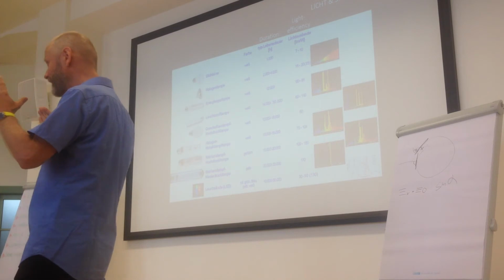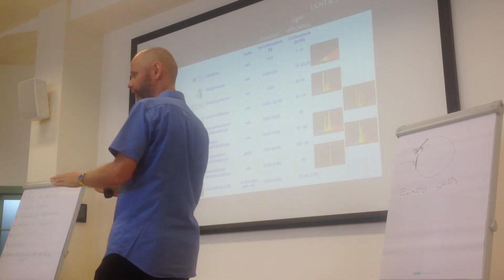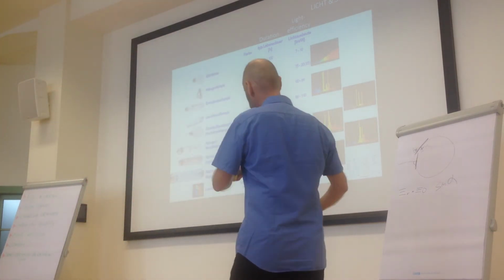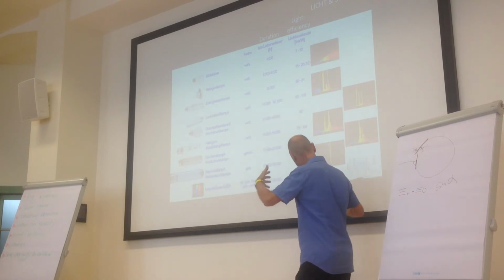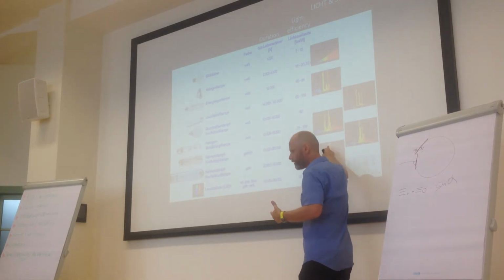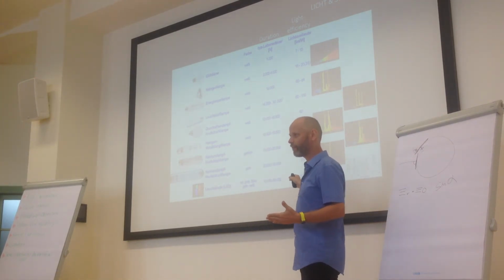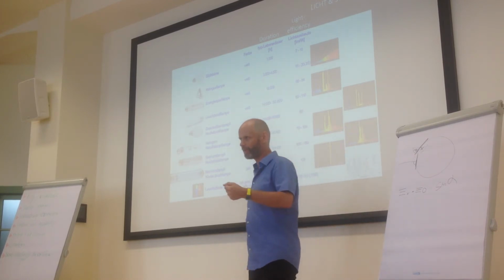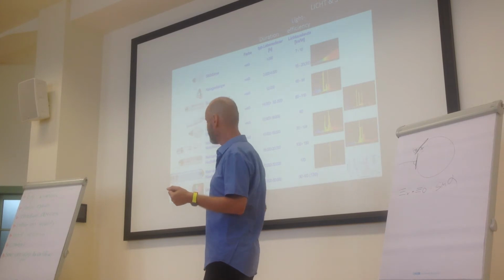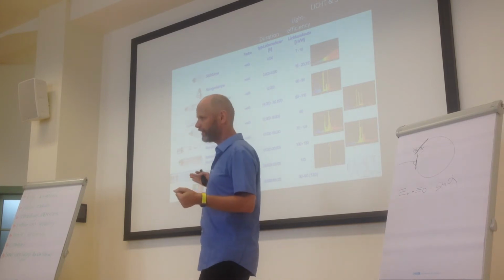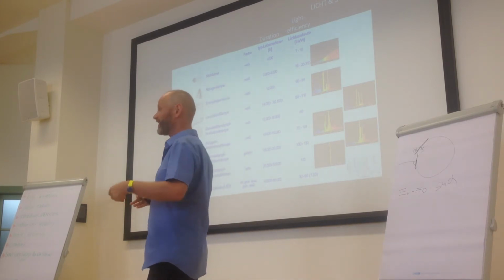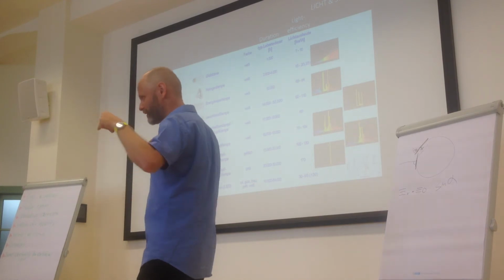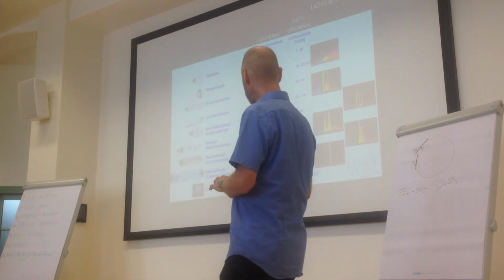Because you can't see clearly the color of the liquid. You can basically see just this wavelength of about 555 nanometers. So the energy efficiency in this case is very high, but the color rendering is very, very low.